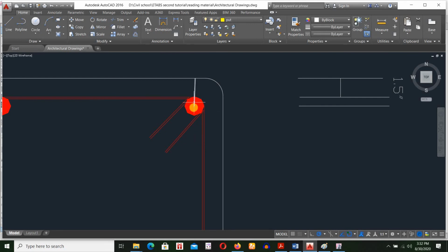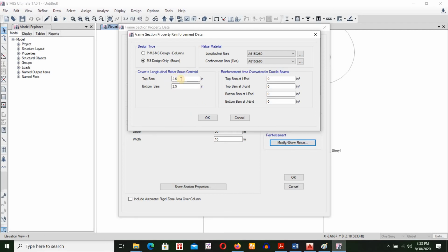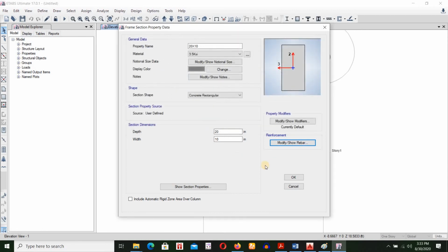The radius is going to be 0.31. So if we add that up, it's going to be 2.3 inches, but we're keeping it at 2.5 inches because 2.3 inches is easy. If we write it here, it's easy to write, it's easy to model, but when we're going to actually construct the beam, it's going to be hard to get a 2.3 inches. So let's keep it at that.